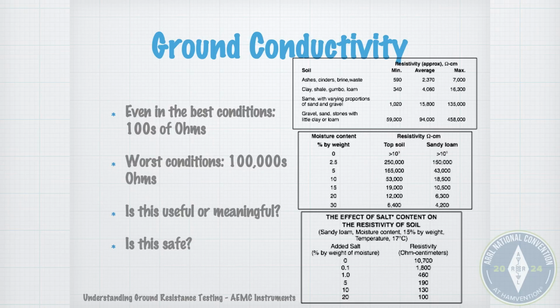So this is interesting information, but you have to be aware of it when you're setting up any kind of system. You know, if there happens to be current flowing in that particular direction, this might not be a safe situation because there will be a gradient across there. So just because we stick it in the earth doesn't mean it's a common conductor. And that's useful, but it may or may not be safe.